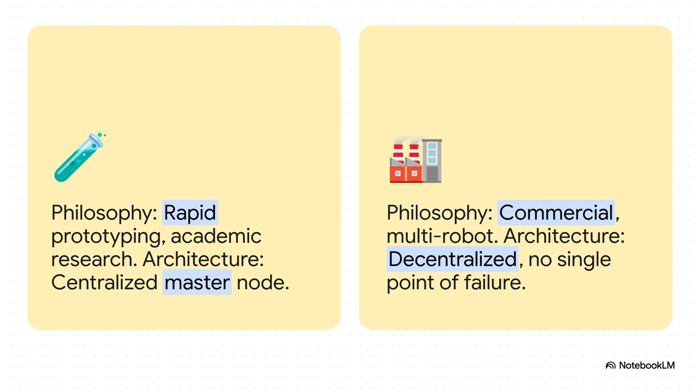The biggest, most fundamental change is right there in the architecture. You see, ROS1 had this central master node. It was the traffic cop for the whole system. And if that master went down, poof, the whole system collapsed. So ROS2's first big move was to get rid of that single point of failure completely. It went decentralized, adopting an industry-standard communication system called DDS.